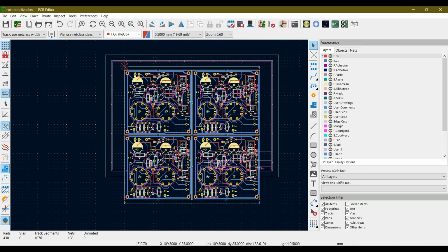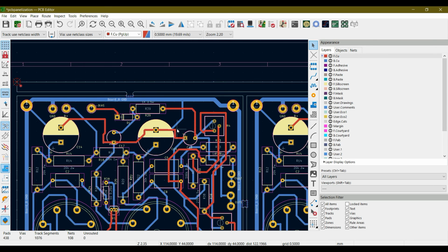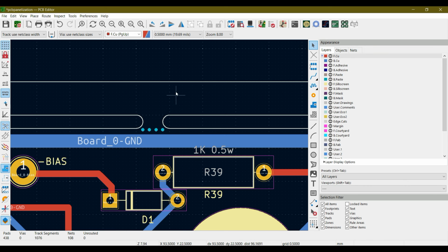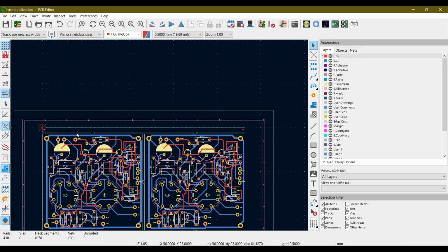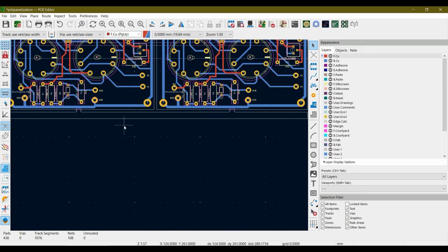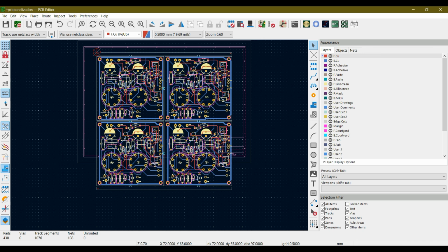The next thing we have set is the framing. Over here on the top you can see this one from this mouse bite above. Actually this is one rail over here, a frame rail, and the other is over here. These are actually an extended PCB that will be placed on the conveyor while we are going to solder these components in a reflow oven. So these are the framings over here.